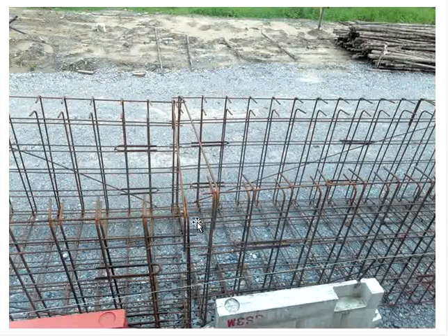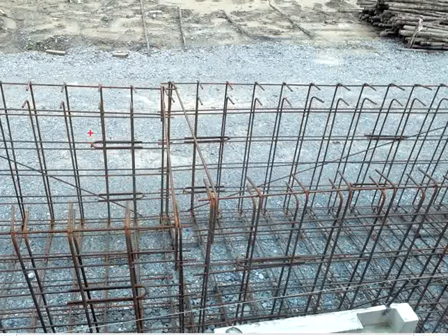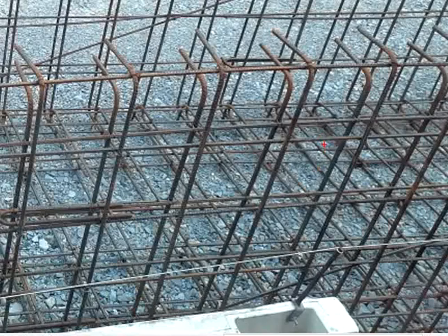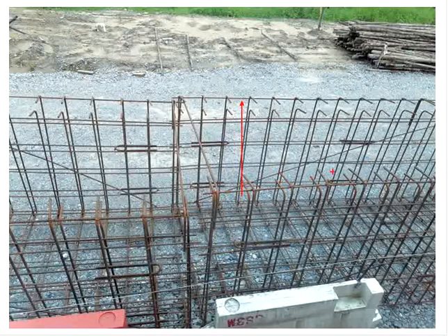What is interesting when you see the design, they use this as the spacer for the 2 layers of reinforcements of the concrete drain. As for the base of the drain, double layers is also provided. You may observe how they put their reinforcement. This gives you some ideas how to produce the detailings for the drainage. Due to the high effective depth here, you will need transverse reinforcement to control the cracks, the surface shrinkage cracks.